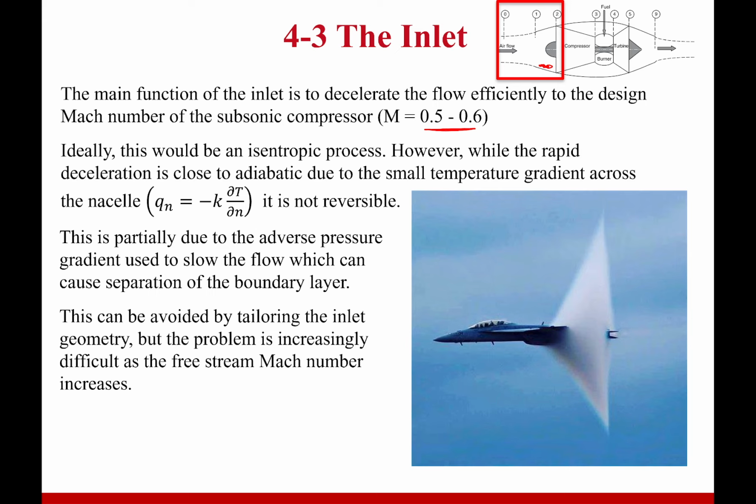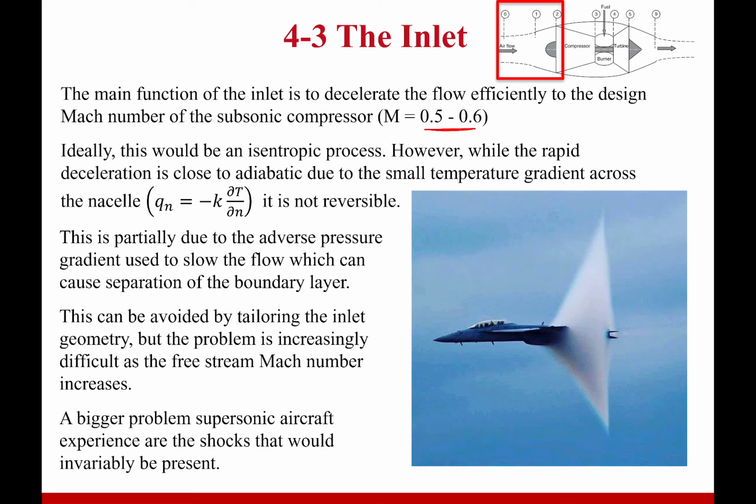Now, we can get rid of that if you tailor the geometry of your inlet properly for your particular Mach number. You can actually make it stay attached. Though as you get to faster and faster Mach numbers, higher and higher above 0.5 and 0.6, this gets worse and worse and more difficult. Now, for supersonic aircraft, there's a much more obvious problem, which is simply that there are shock waves. Okay, you have a shock wave that's already making it irreversible just to begin with. But if we're subsonic, then it's mostly just going to separate. That boundary layer separation is our biggest problem.